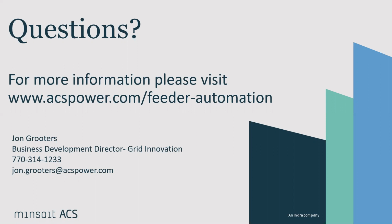So obviously, we'll give precedence to restoring customers when a fault has occurred. Then, following the fault and reconfiguration, we can take a look at the conditions on the circuit according to the IVVC objectives, and see if there are actions that can be taken by the system to re-optimize based on the new feeder topology. Okay, great.